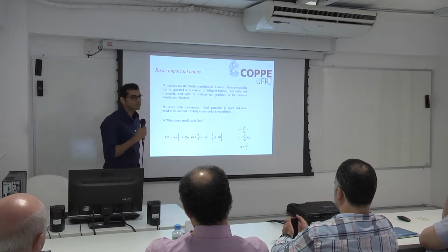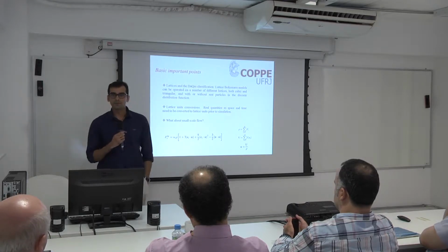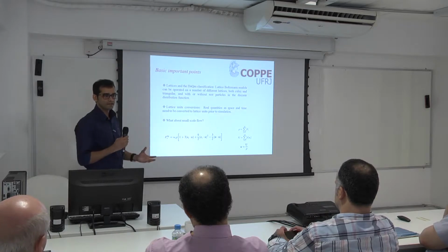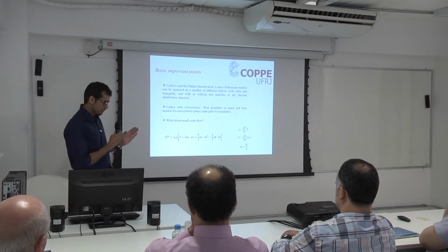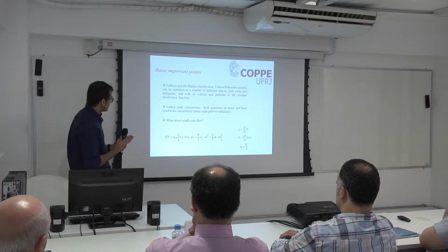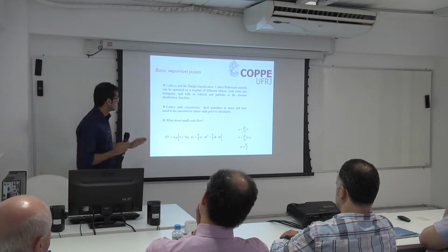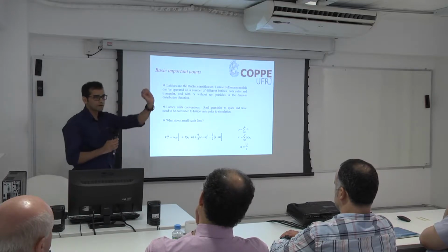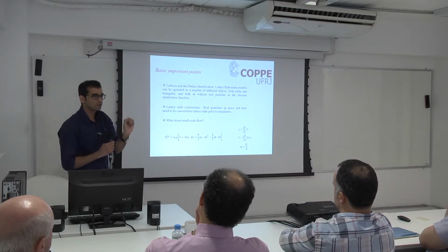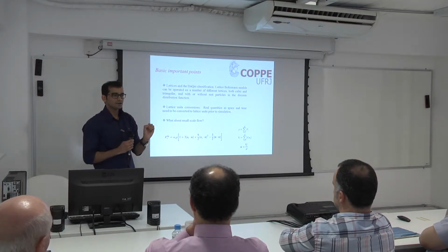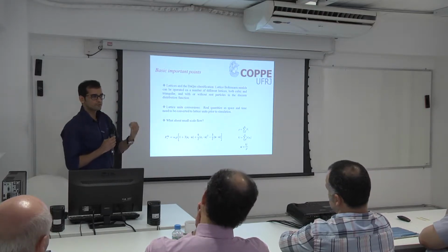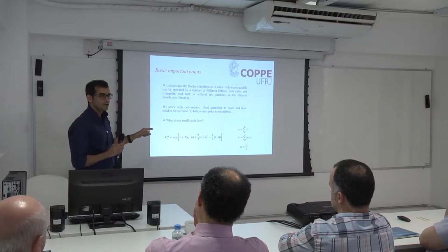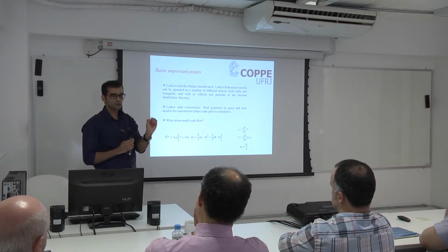Now, what about small scale flow? Because we are talking about pore scale modeling. We are not talking about the thermal and other cases like we generally have in CFD. We are talking about the pore. Imagine that at the pore scale, the lattice points are extremely close to each other. So if we use the velocity of sound to define our intervals, the space would be extremely small.